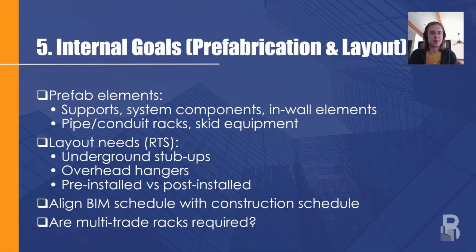Your team can go out there with a robotic total station, or RTS, and with all of those points from the coordinated BIM from the BIM coordination process, sorry, translating those into the field. So then those can get translated up to structure, and in order to aid your layout, get those tape measures out of your field team's hands.